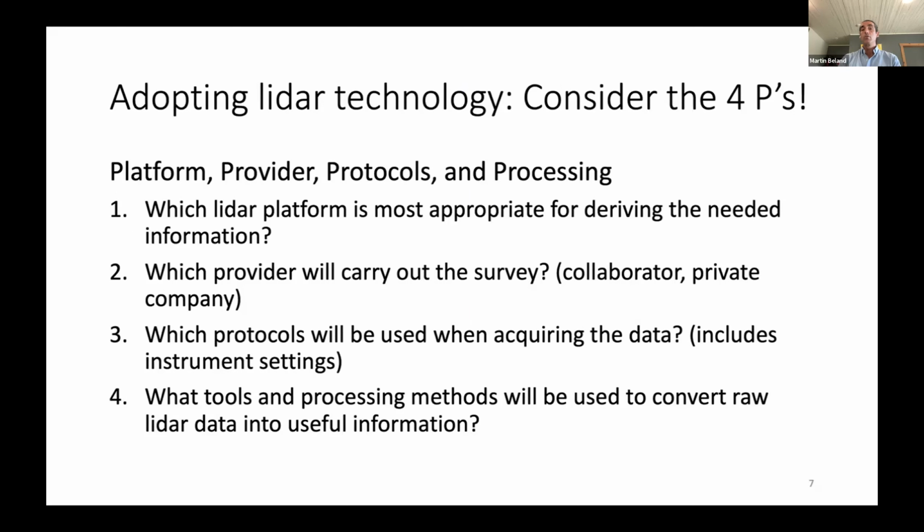So when we're using LiDAR systems at flux sites, mainly I separate in 4 different categories of things we need to determine. Which platform you're using: is it airborne, UAV, or terrestrial? Who's going to carry out the survey? Sometimes you do need some expertise to do this, so it can be a collaborator or a private company in some cases.